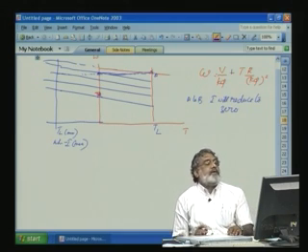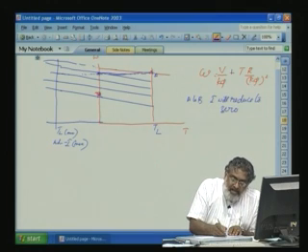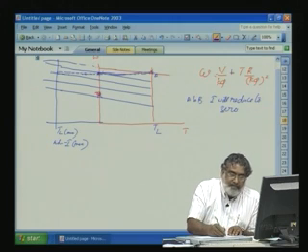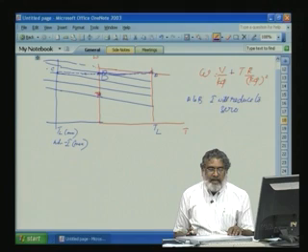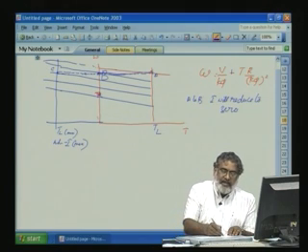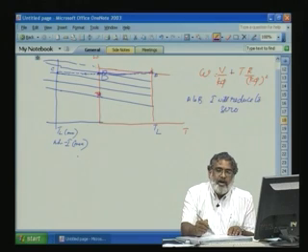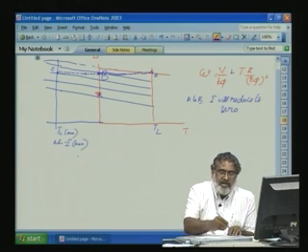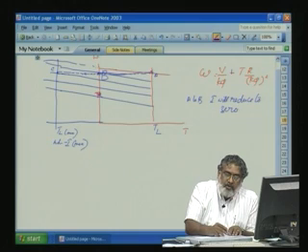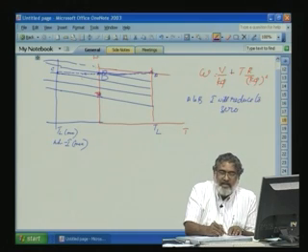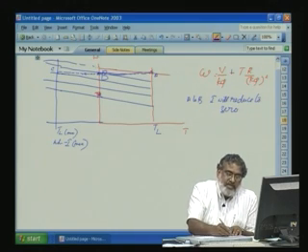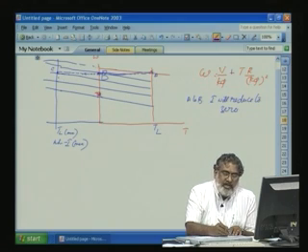Maximum negative. Now, what happens? So, from here to here, the regeneration starts. This is B, it will come to C. Regeneration starts. So, in this region, torque is negative. So, load is supplying power to the machine. Now, the regeneration starts, machine will slowly decelerate. So, A to B to C, the current changes very fast. Now, at C, the mechanical time constant will come into picture and this will slowly reduce.